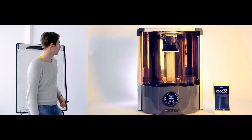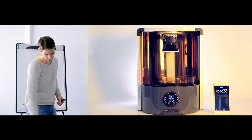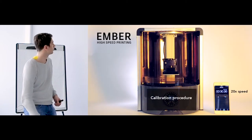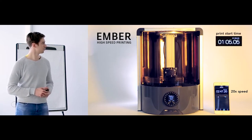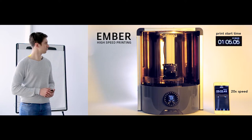So let's take a look at the next one. It's also on stereolithography, but for the bottom-up method. So this is the desktop printer called Autodesk Ember. Here's a demonstration of high-speed printing on Ember. For the first 11 layers, the tray uses a sliding mechanism to separate each layer. However, after that, there is enough space between the build head and the tray window so that the suction force is minimal. The Ember now pulls directly upward after each layer.